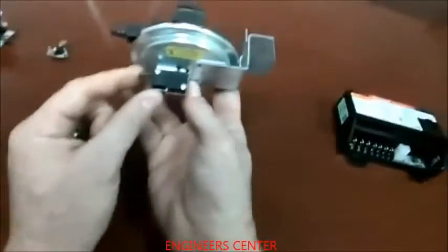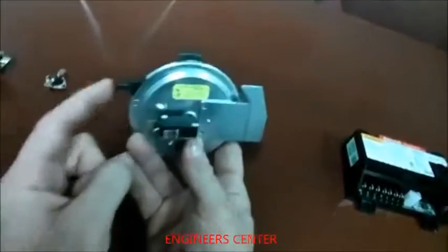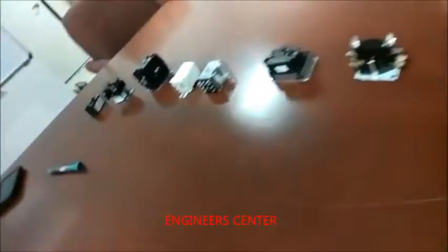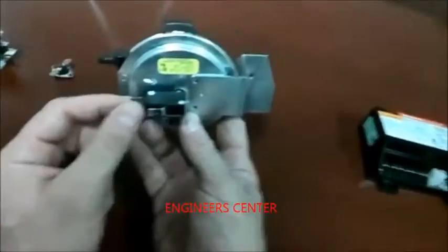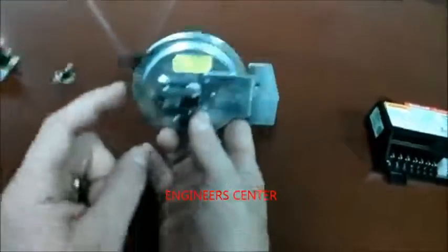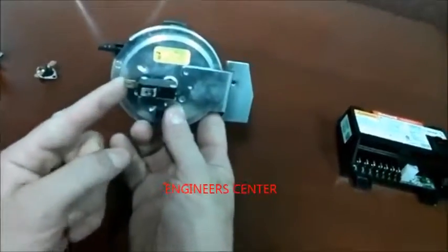Here, we have another. This is a pressure switch, but it's just a relay, guys. It just opens and closes, but this one opens and closes according to pressure. So just like the rest of them, it'll open and close. You know how to test this. You know how to test all these things, because all they do is open and close. You get a meter, you put it on continuity, see if they open and close, or you just get your meter on voltage, and if you have voltage here, and it doesn't have voltage here, then you know it's open.